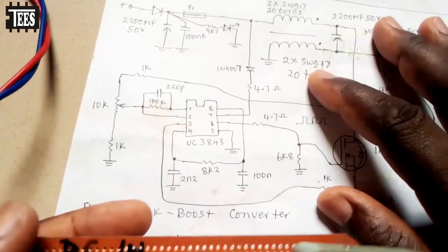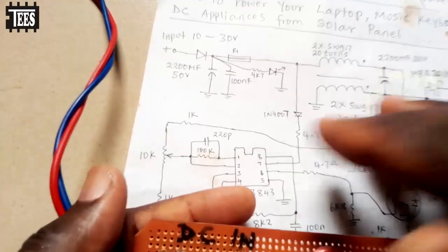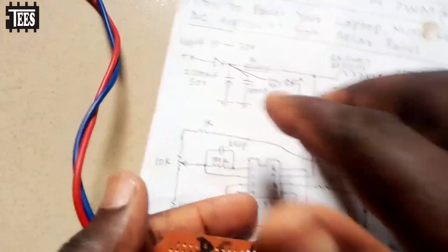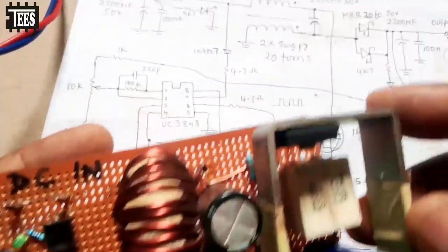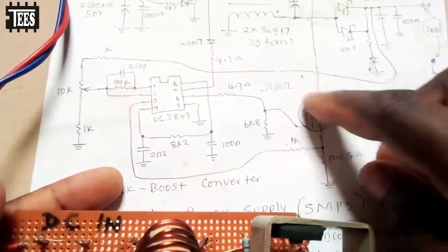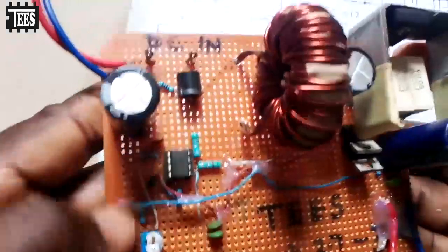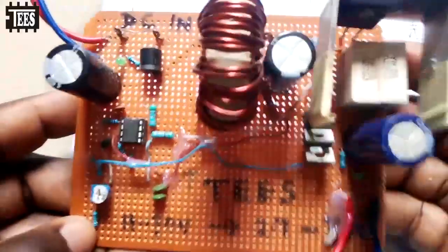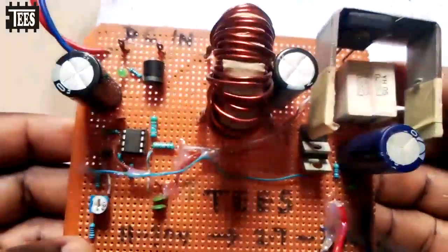So this system here can operate. Now your input needs to be 10 amps and above. So your input should be 10 amps and above. So take note of that. So this heat sink is very necessary. This one gets hot, so that's why you must put some aluminum heat sink. This is a heat sink I put here, so you can see. And if this is going to be running for longer hours and you are drawing much current, a cooling fan is also necessary. You understand?